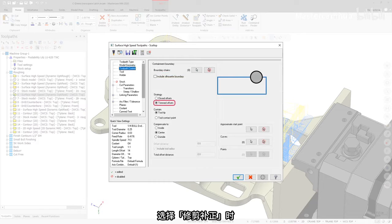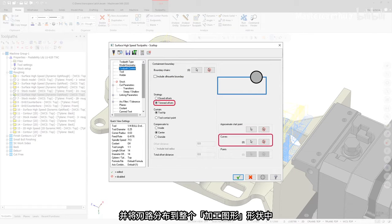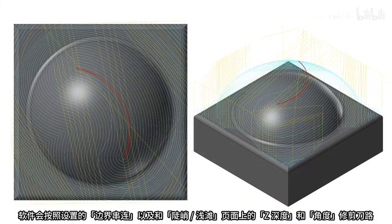When trimmed offsets is selected, Mastercam drives the toolpath from the selected curve or outer shape of the machining geometry and is then generated across the entire machining geometry shape. The resulting motion is then trimmed to the boundary chains and the angle and z-depth values on the steep-shallow page.